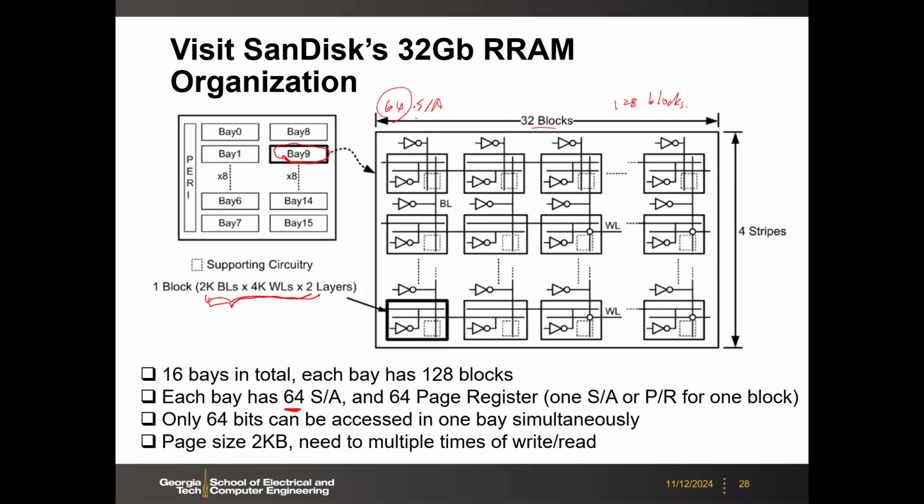You see here, this is unlike the SRAM or the DRAM design you have seen before. Even each bit line, you have 1 SenAmp, right? If each bit line has 1 SenAmp, then you have like 2 kilo in one block, or even 128 times 2 kilo for one bank if each bit line has its own SenAmp. So that means this is not local sensing. This is shared. The SenAmp is shared across the entire block.